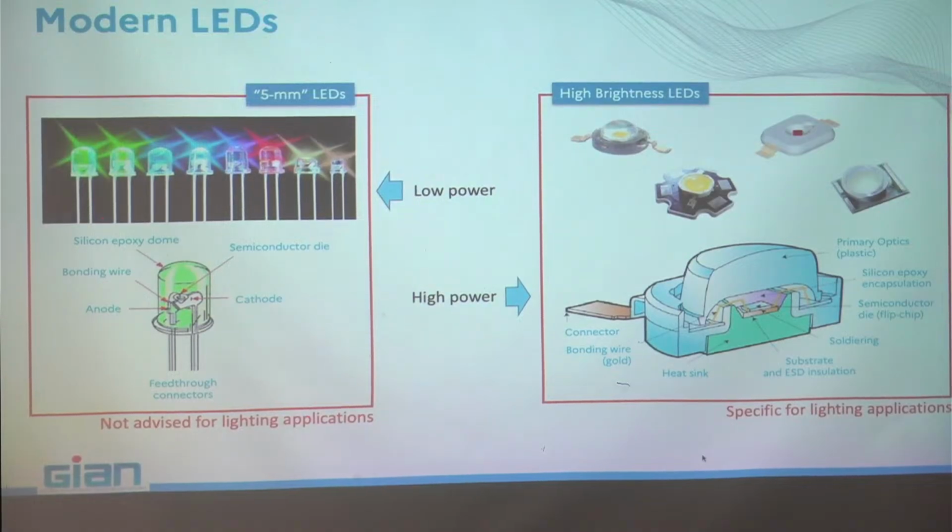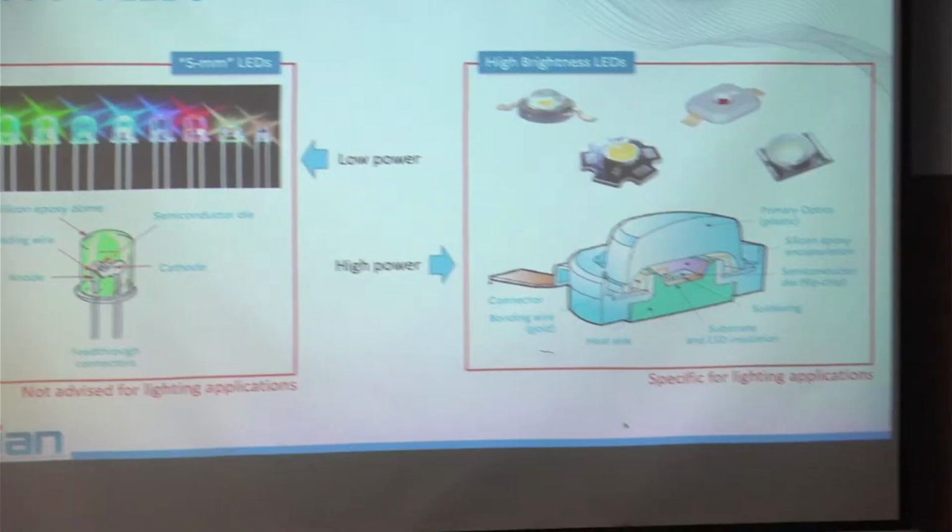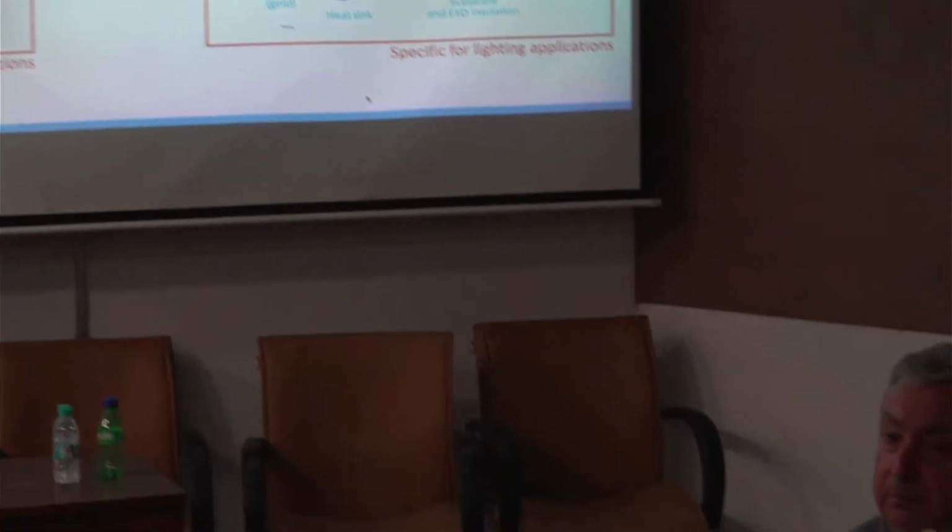This kind of LED is low power. You are staying here below 500 milliwatts input power, and they produce very little light. They are not a good option for lighting. Today you can find some lamps using such kinds of LEDs, with many LEDs in that lamp. It's absolutely not advised to use such devices. They are completely unreliable and useless.